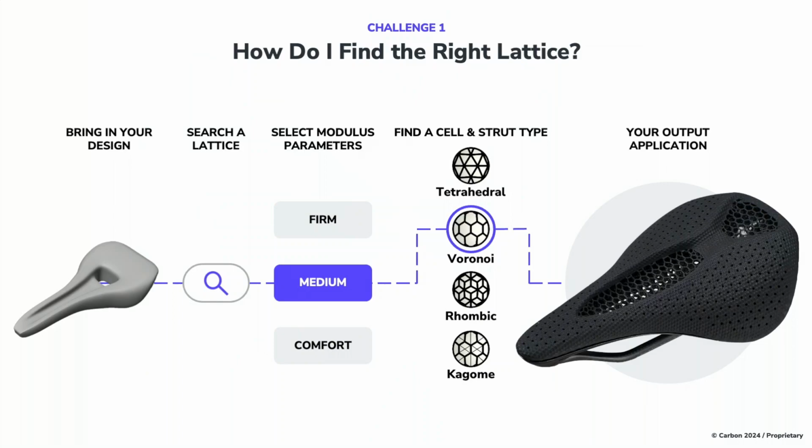You need to be able to communicate this, and a big part of answering the question of what I need in terms of properties is to start off by asking, am I designing for a marshmallow, a pillow, or a hard hat? Where are we in the space of mechanical properties? From there, you can really get quantitative and pick out your resins. Certain resins might do better at damping, others more for energy return. Look at your particular lattices for different aesthetics or different types of mechanical response. Maybe you want something that buckles more, so you have basically a constant stress profile, or maybe you want something that's a little bit more nonlinear, like a foam response.